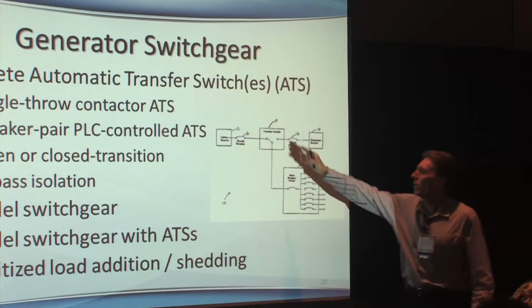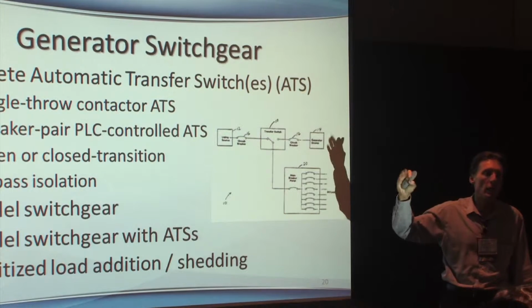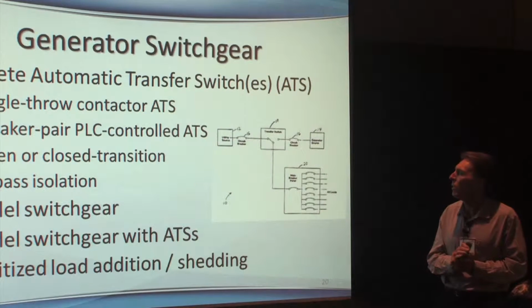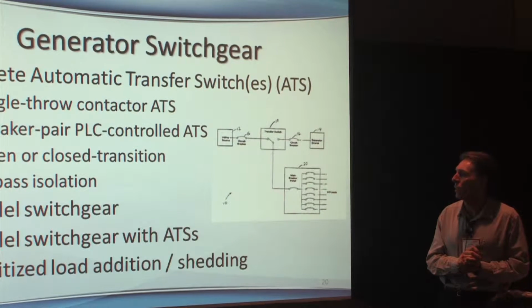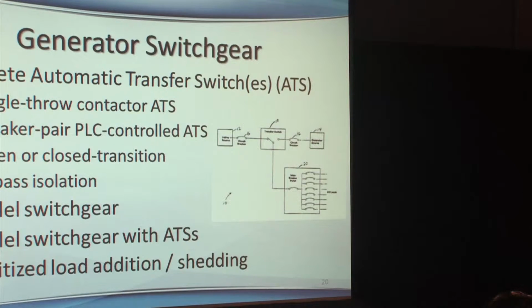So certainly this can be a very elaborate parallel switchgear with anything from load demands that determines how many generators you need to run if you've got a multiple generator facility, as well as if you've got more load than the generators can handle. You can put in load shed controls to automatically turn off things that aren't as important, such as comfort cooling, that sort of thing.